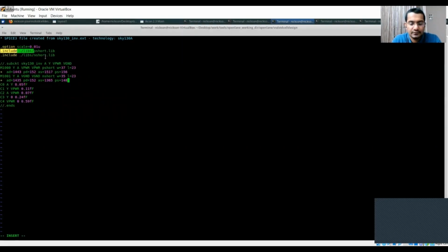Now we need to make the definition for the supply voltage first. So we will create a variable VDD, which is connected between VPWR and the node 0, which has a value of 3.3 volt. So this is creating the supply voltage. Similarly, we create a VGND. VGND is already there. We create VSS. That is the voltage connecting between the VGND and 0, whose value is 0 volt. Fine, the ground and the supply is done.